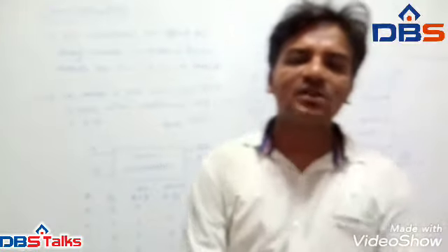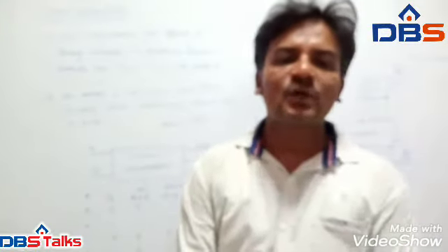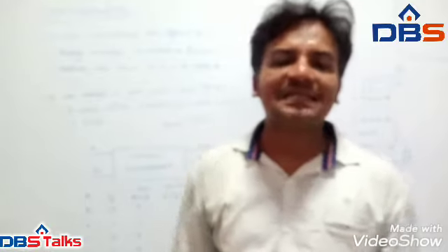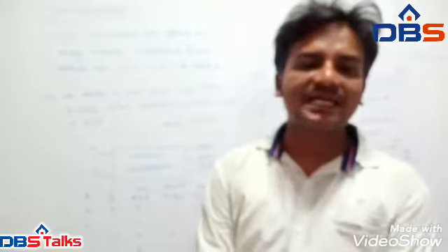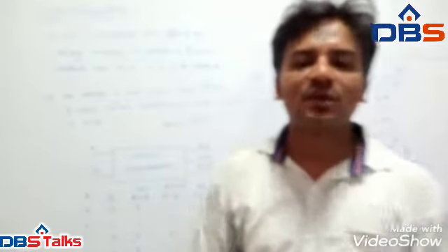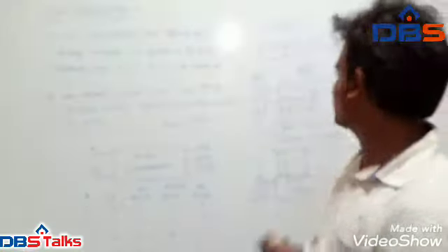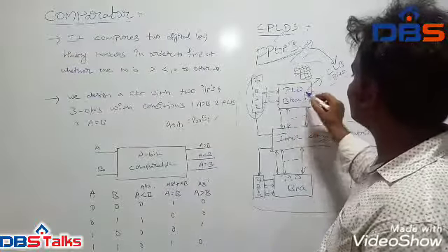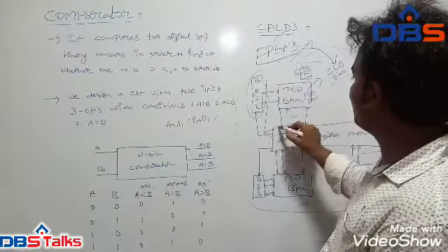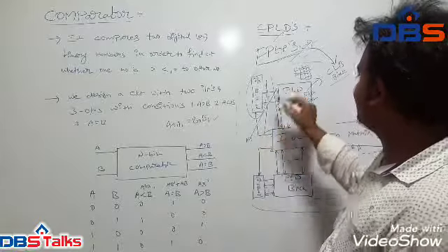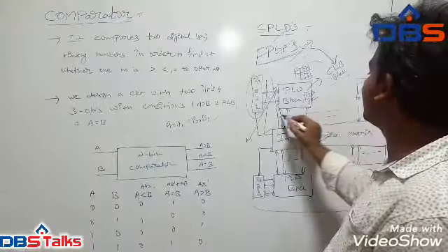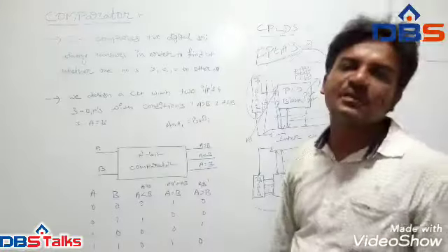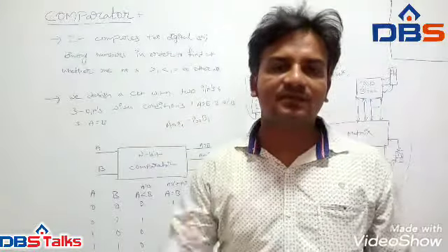These logic blocks are arranged in a two-dimensional array, and the interconnection wires are organized as horizontal and vertical routing channels between the rows and columns of logic blocks. Wherever a CLB is present, we have vertical routing and also horizontal routing for each and every CLB block present in the design.